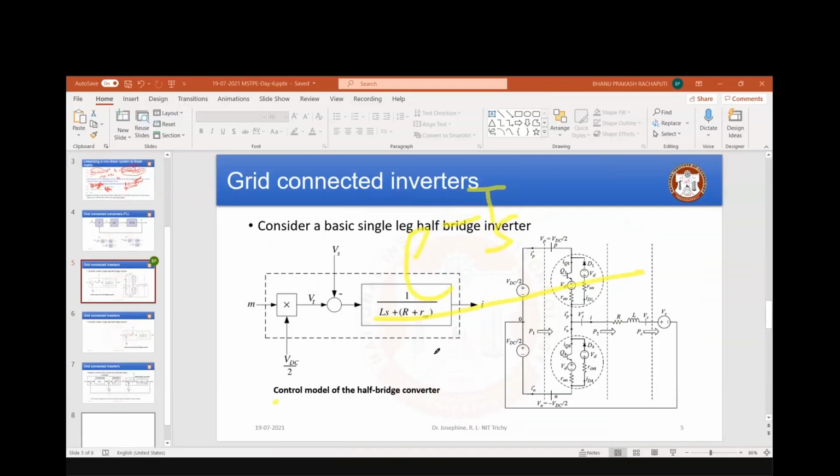If they have this first order differential equation, there are some methods like Ziegler-Nichols and IMC, and even there is one latest method. So that kind of network can be easily implemented, and you can tune the KP, KI values and get that output. They don't want much complexity. They just know those, and they will apply Ziegler-Nichols if they want.